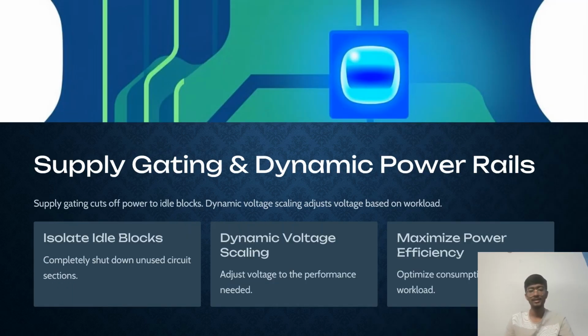Supply gating and dynamic power rails. Supply gating cuts off power to idle blocks. Dynamic voltage scaling adjusts voltage based on workload. First, isolate idle blocks. Completely shut down unused circuit sections. Second, dynamic voltage scaling. Adjust voltage to the performance need. Third, maximum power efficiency. Optimize consumption for the workload.